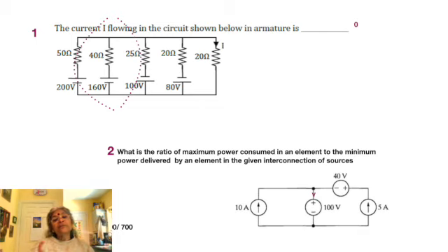We have a similar situation in the 100 volt source in series with 25 ohm given alongside. A little next to it, the directions are different, so we have a circulating current. This is the speciality of these circuits. We can see a circulating current there, wherein the current that goes up through the 200 volt source comes down via the 100 volt circuit, because the resistors and the sources match.